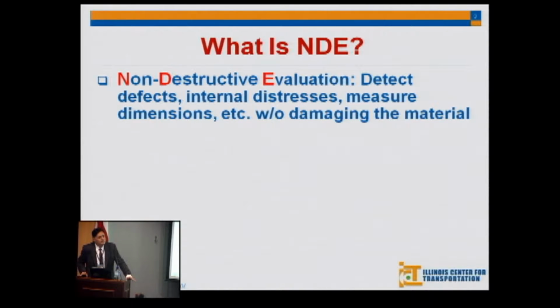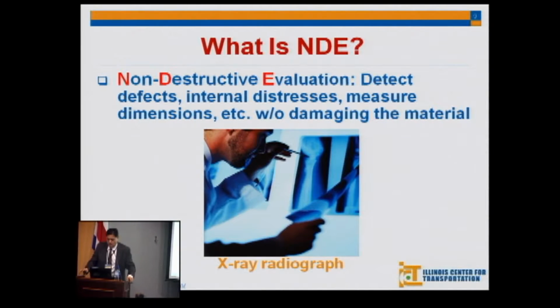So before we start, we talk quite a bit about non-destructive testing. So what is non-destructive testing? In a simple way, it is trying to detect any defects or distress within a material or within a pavement section or a bridge or any infrastructure without doing any damage to that infrastructure. A good example is if you go to a dentist and you do an x-ray for your teeth, you cannot see a decay, but the x-ray will show you if there is a decay in your tooth. So in a very simple way, we'll be able to see what we cannot see with the naked eye.